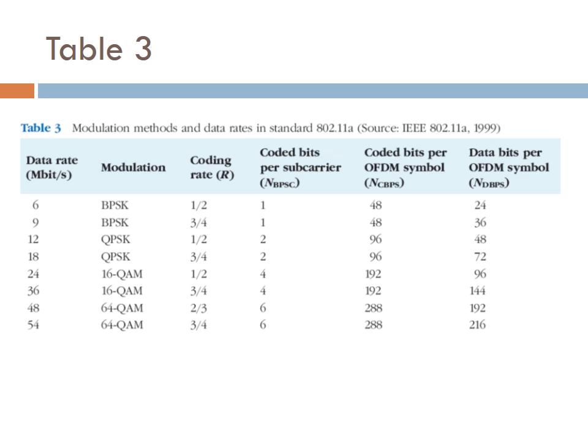The coding rate tells you the ratio of x to y. Thus, for example, in row 1 of the table, the coding rate column tells us that for every 1 bit of original data, there are 2 bits of data in the coded version that is actually transmitted.